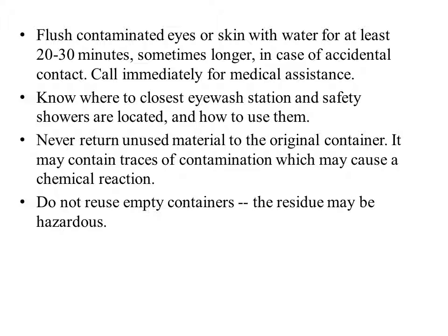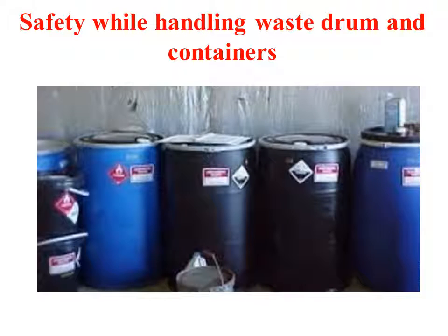That means once a chemical has been taken out of the container, it should not be returned back, because there are chances that it may be contaminated and it may cause a chemical reaction. Lastly, we should not reuse empty containers. We should never reuse any empty chemical containers, because there are chances that there will always be some residues present in those containers. So empty containers should be properly disposed of as specified by the manufacturer.